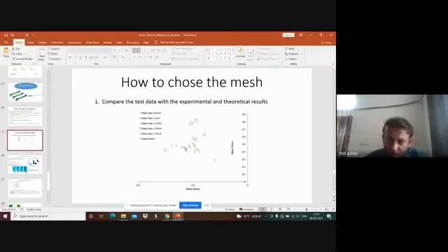So which is my experimental data? Something which is in this cross. If you look at this cross, you will see that in this particular range, your data is accurate. This particular range is given by the red and blue triangles, which mean 1 and 1.5 mm of mesh size. So 1 and 1.5 mm mesh size is going to give us an accurate result.